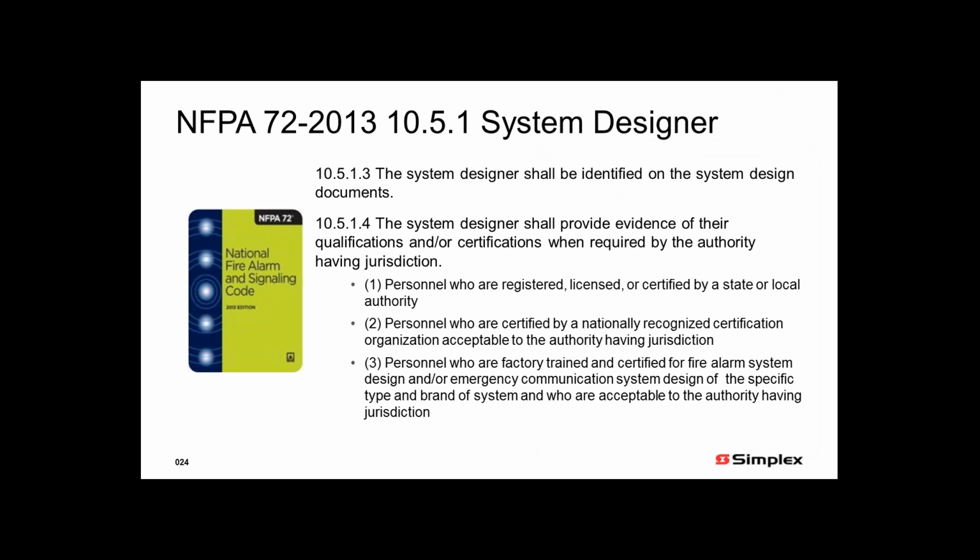Well, that's in 10.5.1.3 and .4. And we talk about, first off, in 10.5.1.3, the system designer shall be identified on the system design documents. When I unroll those floor plans, the blueprints for my fire alarm system, and I look at my title block, it needs to be identified on there who's the system designer, not just that it was Simplex or Peter Ryan's fire alarm company. It needs to tell me who the person was that did that.